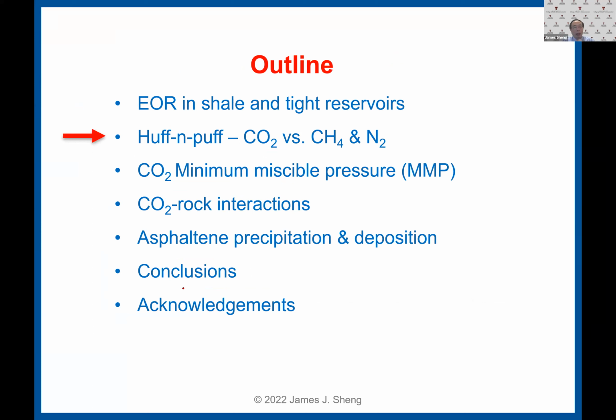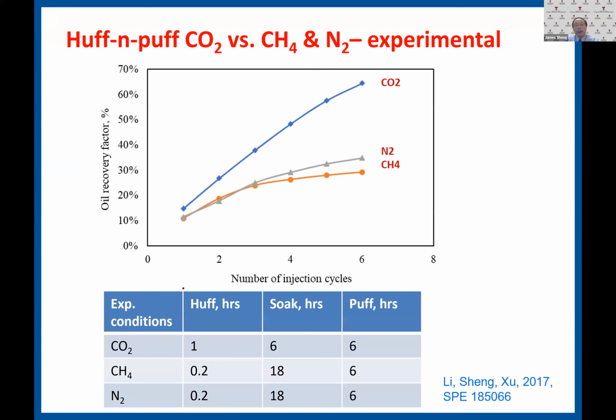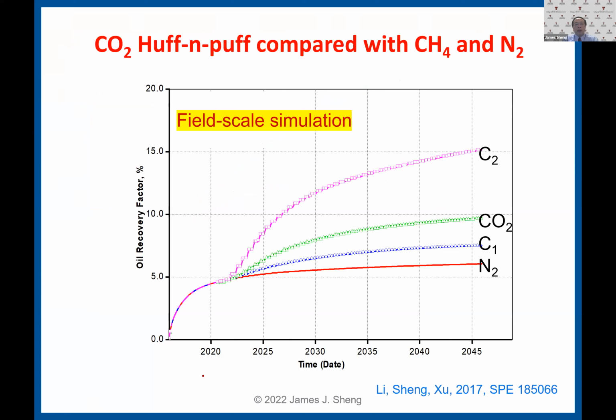Now next, in terms of huff-n-puff, let's see which gas is better. So we did this experiment work. Here is oil recovery, and here are different cycles. This is CO2, this is nitrogen, this is methane. CO2 oil recovery is much higher than the other two gases. Here are detailed experiment conditions. I'm not going to elaborate too much. Okay, that is the experiment data.